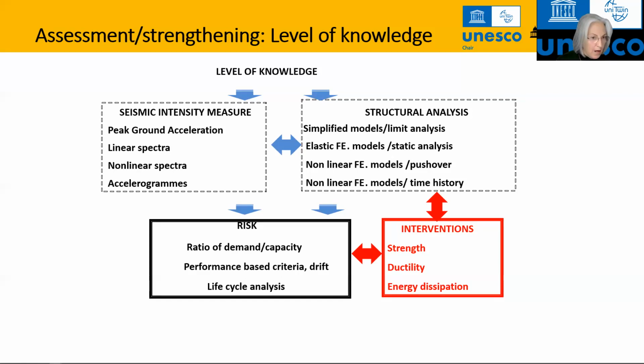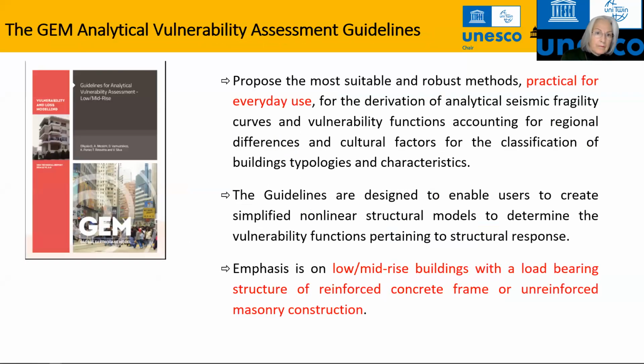a totally probabilistic definition of the hazards with accelerograms in the nonlinear range, we are in a position to determine a complete life cycle analysis of the structure and therefore understand what their residual capacity is and so on, and look, for instance, at energy dissipation approaches. Therefore, the level of knowledge at which we set ourselves at the beginning and the level of information that we have on the hazard then influence all other aspects of this process.